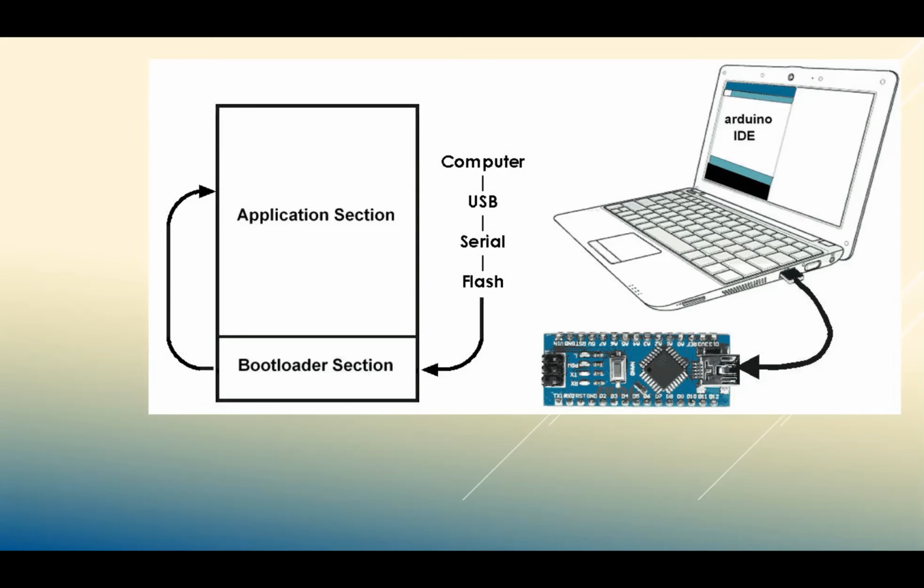The bootloader itself then takes up some memory. The old bootloader and the new bootloader. The old bootloader used 2K of memory. And you probably saw it way at the beginning when we looked at the spec. So it allocated 2K, anything above 2K could be the actual application, anything below it was reserved for the bootloader. They then wrote an improved and faster bootloader than the old bootloader.